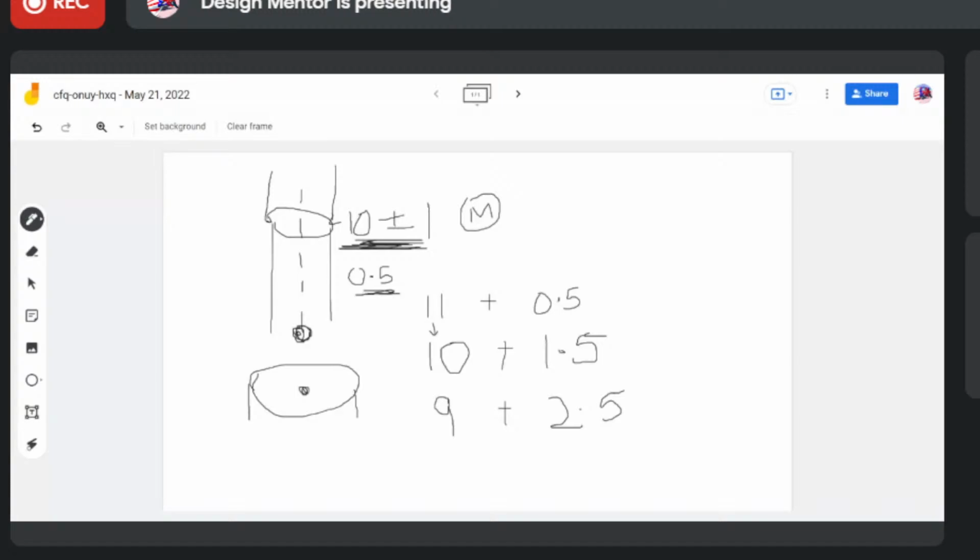2.5, what will you add? Material or what? No, not material. That the shaft can go 2.5 mm here and there. 2.5 is a lot, that won't be realistic. Yeah, I know, that is just an example so you can understand. If I say 10.005, then the example becomes tougher to understand. Keeping it simple.